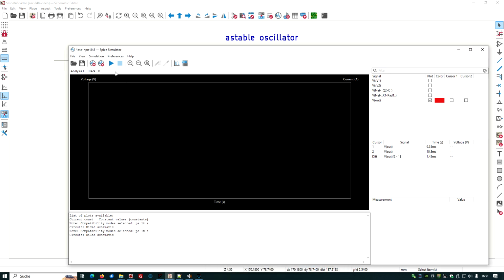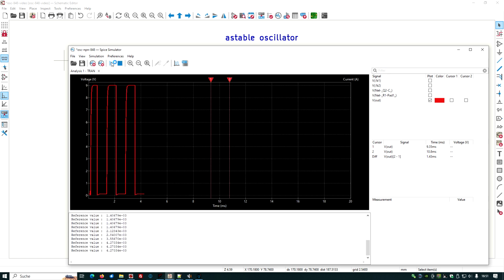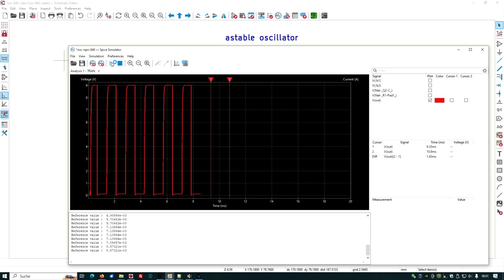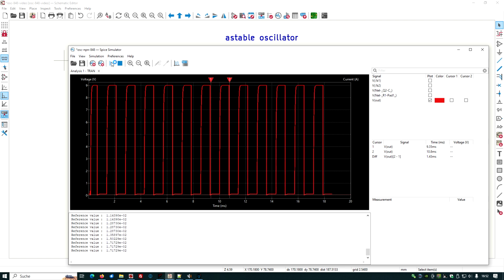Okay, let's just try to do that. Starting here. And I see, oh, this thing is indeed oscillating, but a little bit strange. Not a very smooth ride. It oscillates sometimes faster and then slower again. And what you see here, the number of data rows is about 200,000. So not 20,000, but 200,000. Something has happened inside of the simulator which leads to this critical result. Even if it looks nice, a factor of 10 simulation time increase, that's not what we want.